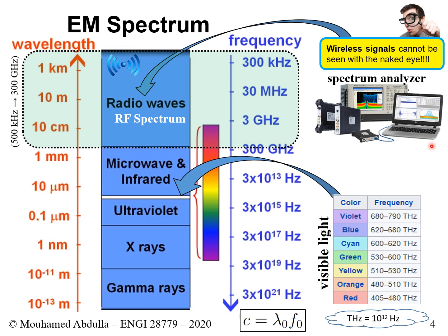And so there are different types of spectrum analyzers. If you see here, maybe the picture is a bit too small, but this is a spectrum analyzer that is connected with your USB cable. So it's a small one. It's an SDR, software-defined radio spectrum analyzer. So you connect this device to your computer with a USB cable, and then you download an application, and then the screen of your laptop becomes your spectrum analyzer using this tool.